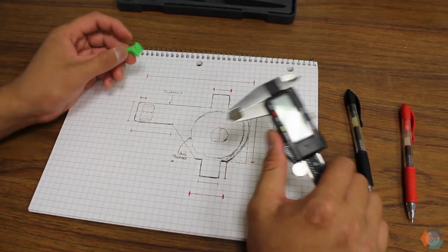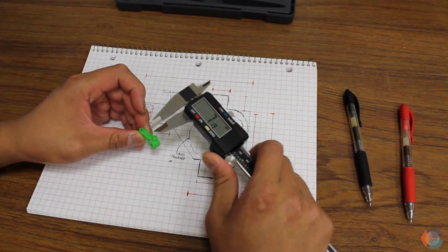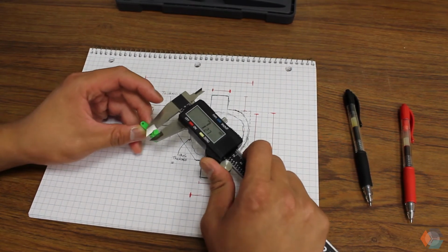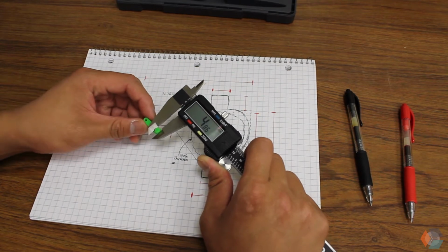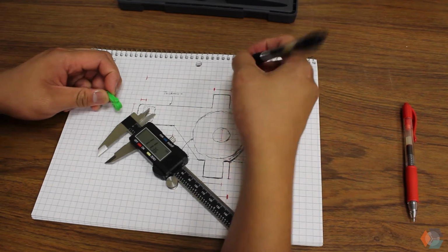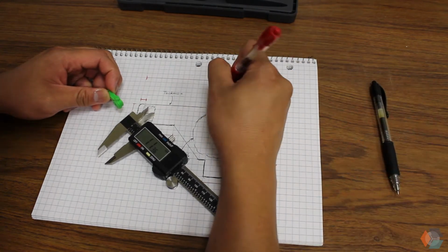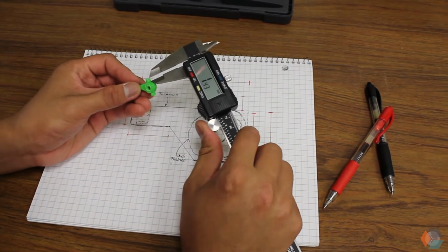Now, we're going to use a caliper to determine some of the key dimensions of the part. Say, this top part right here. So turn on the caliper. In this case, we're using millimeters, but you can use other unit formats if you want to. So the cylinder I want to join is 4.86. So we're going to write down that value here. 4.86 millimeter, all the way right to the unit, just so you don't forget.